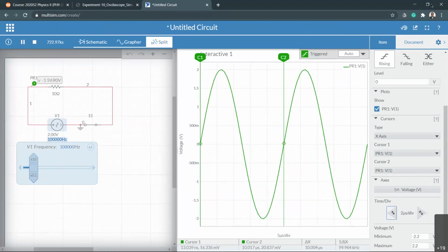Change it back into 2 microsecond per division. Now, since it is not updating, you can't read this number right here on the bottom directly. Instead, what you have to do is read how many segments are in between the cursors: 1, 2, 3, 4, 5, and then 5 times 2 microsecond. Okay, we have to read it that way. Make sense? Following that?